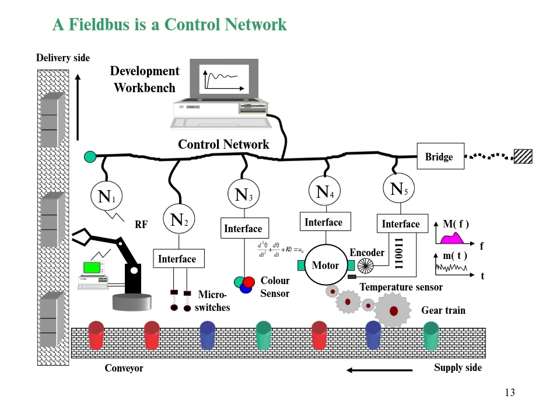Let me talk about the Fieldbus technology. A Fieldbus technology is actually a control networking system using which you can implement distributed control. What is the meaning of distributed control? It's not centralized control, meaning that all the microcontrollers are connected into a network.